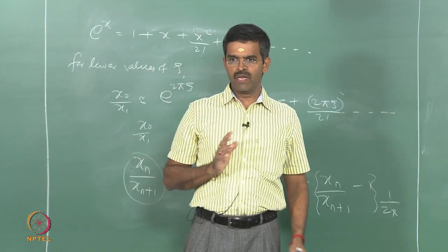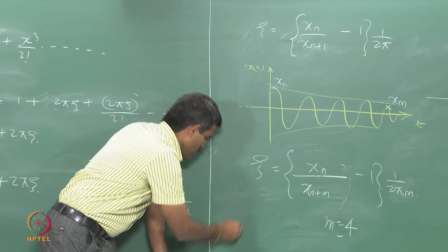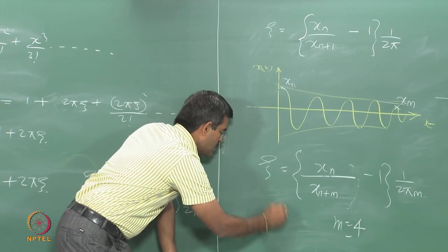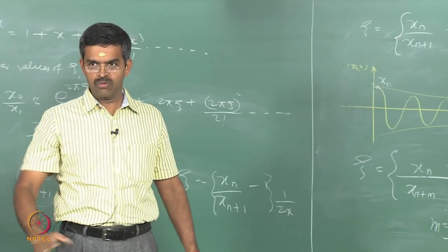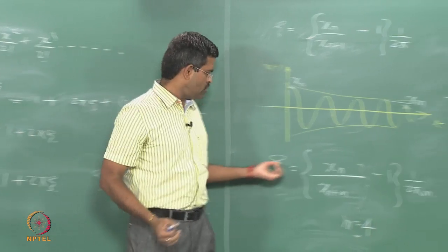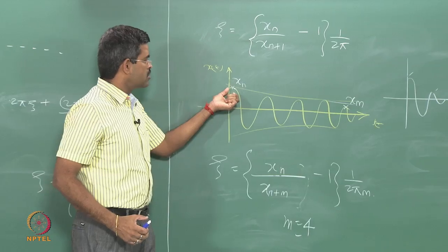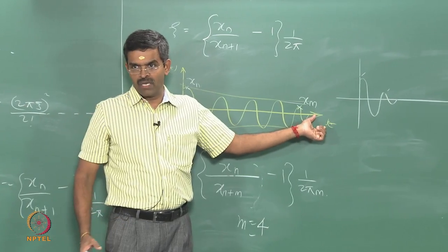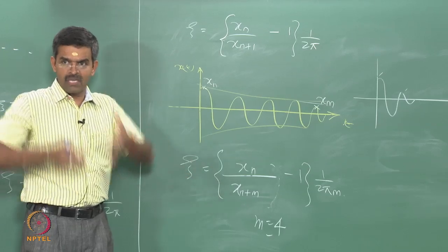Okay. If you really wanted to know from this what is the component of hydrodynamic, what is the component of material degradation and member degradation, you will never get that. You have got to do a separate analysis for this. We can do that, but this equation is highly generalized, which we are interested in. We wanted to actually know what is that ratio which brings the damping or the structure to rest. We are interested in that. Within that, what is the contribution of different elements will be of intrinsic research interest.